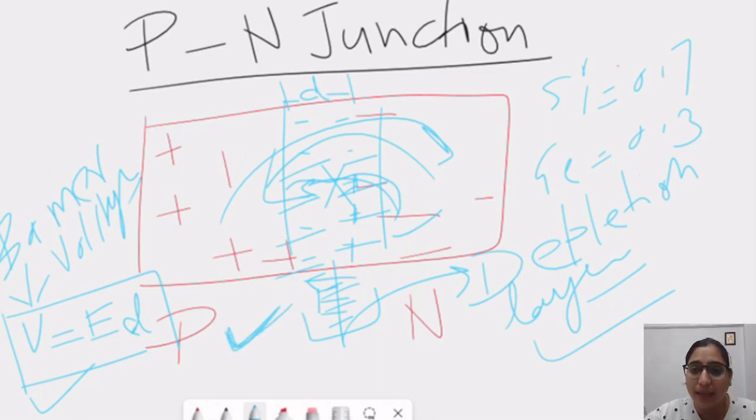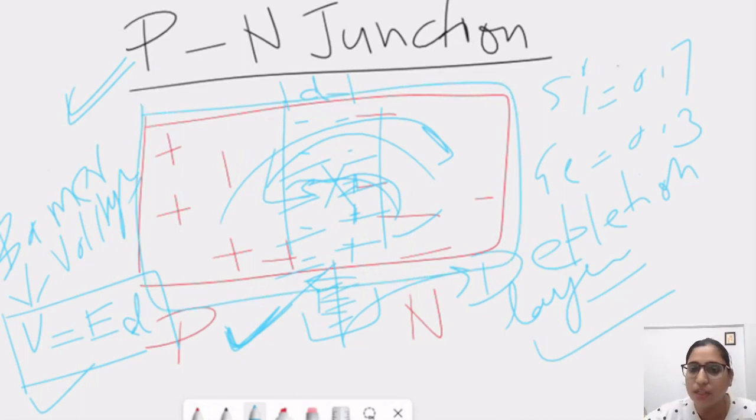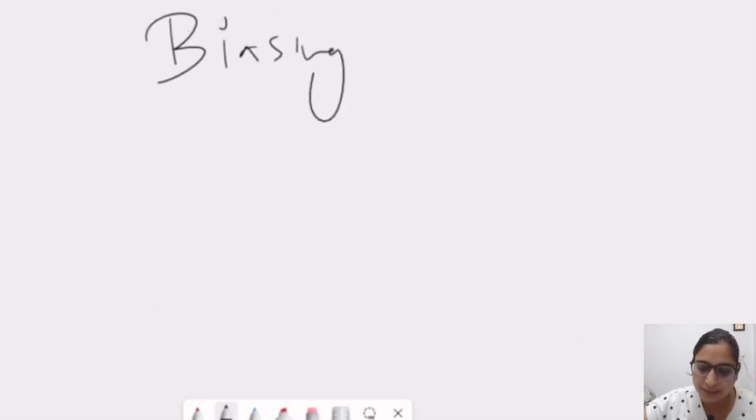As we know, there are active and passive components, and PN junction diodes are majorly active components. So an active component needs a biasing voltage. So here the term biasing comes. Why so? Because if I have to start working with this diode or junction, I need to give a particular operating voltage to it. So this barrier will be removed, and the electrons and holes start flowing and take part in conduction. Let us discuss biasing here. First, we will discuss forward biasing or FB.